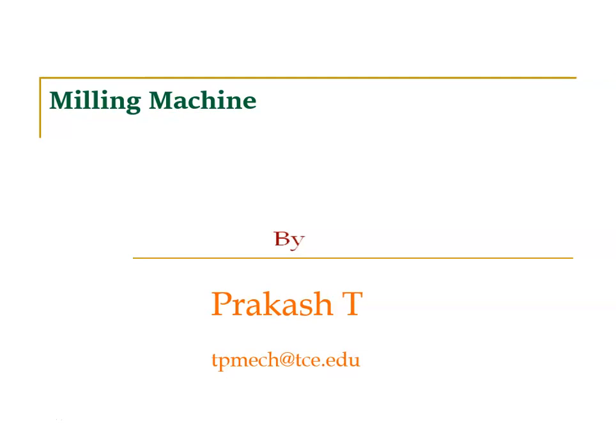Right, so types of milling machine we have seen. We have 5 types: based on the purpose, single purpose or special purpose; based on the working, conventional; based on the structure, column type and knee type. And then the last one is based on the orientation. It may be horizontal, vertical, or universal. Horizontal milling machine is where the spindle rotates about the x-axis. For example, if you raise your hand straight, we say it's horizontal. If you point your hand downward toward the floor and rotate, it will be the vertical axis. Right, so we saw all those things.